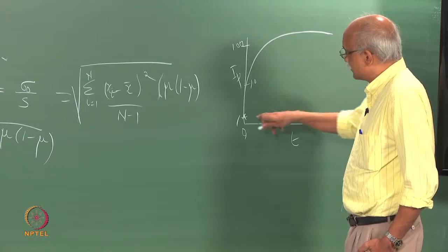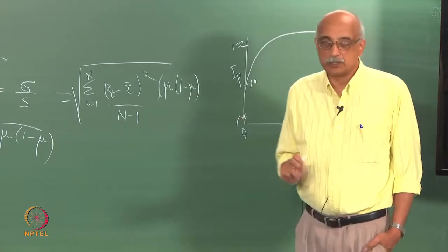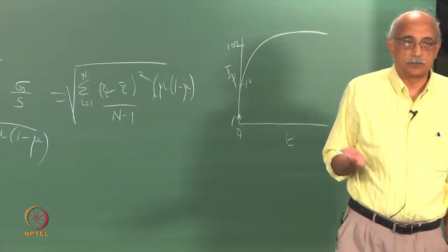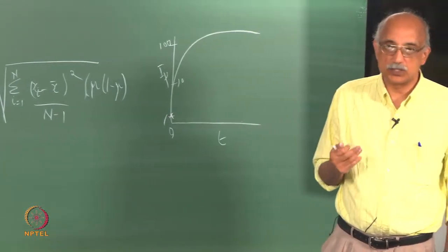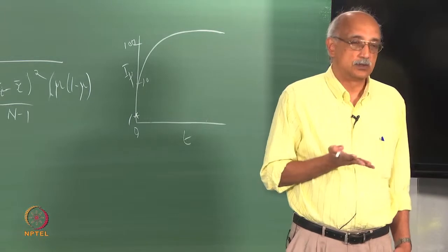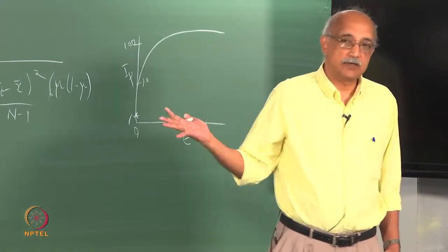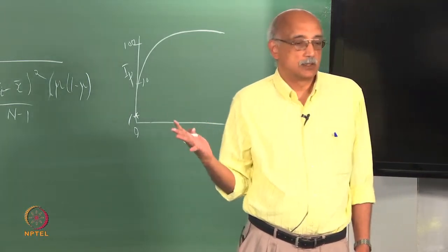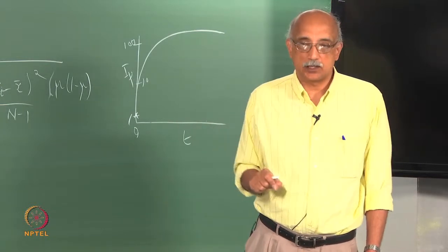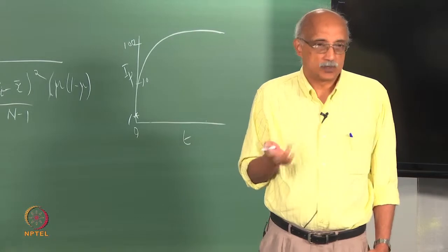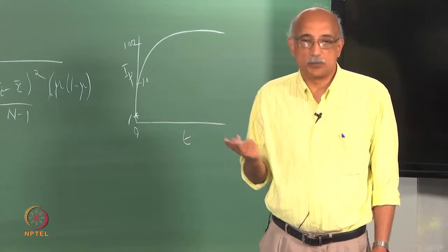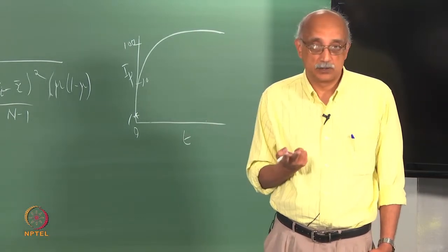What is the theoretical maximum for IP? Infinity, because if you have a really good effective mixing process, eventually the standard deviation should go to 0. In other words, it should be a perfectly well mixed mixture where every value that you take is equal to the mean value, but it never happens in reality for two reasons. One is, mixing is never 100% effective.